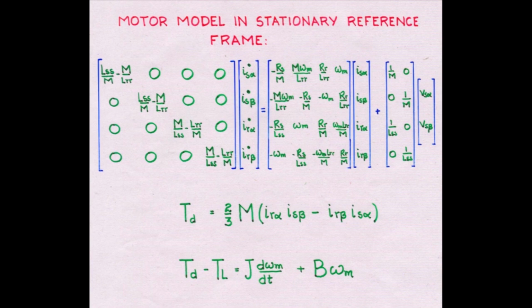So let us see how we implement this. This being a direct equation, we can use the Octave simulation environment for directly entering this motor model and trying to understand the induction machine. We can also put this model in a sub-circuit, make a symbol for the induction motor, and use it in SPICE. We will do both examples and see.